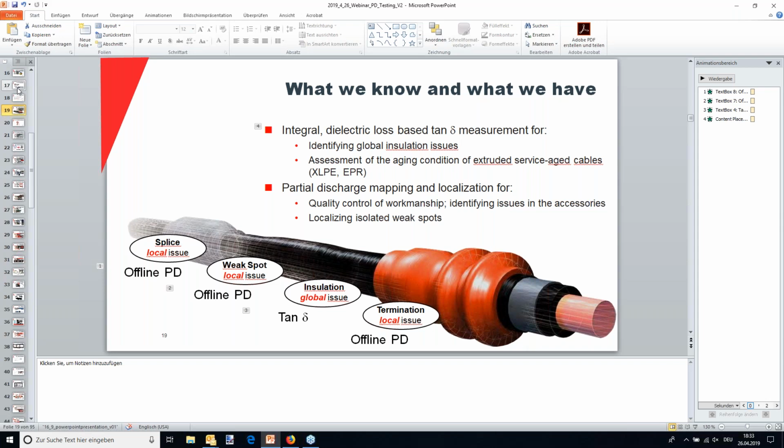I can tell you, up to a few months or years ago, Singapore was the most strict utility when it came to that. They saw a splice that was 500 picocoulomb, they would immediately cut it out, because it's a city-state, a city country, 6 million plus people. The power needs to be on, okay, no risk taken. I think recently I heard because of the success they had with their rigorous testing program, they loosened up a little bit. There was a big study recently in Germany, and a few utility companies participated, and they had numbers like 1,000 picocoulomb, something like that.